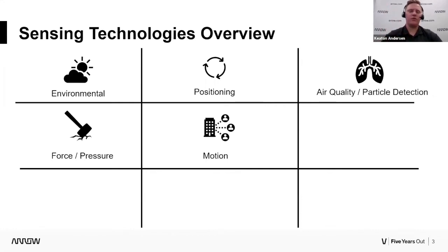There are some that work off of acoustics as well. So when someone walks in the room and it can hear thumping or something like that, those obviously have to be very, very fine measurements. But those are some of the elements that you end up seeing there: both passive infrared and acoustic. And that helps to say, hey, if no one's in the room, go ahead and turn those lights off. And the moment they come back in, we'll flip them back on.